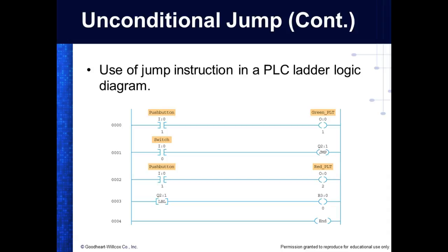What I was getting at within my mind, I'm battling. If I was looking at this in motor controls, every circuit has to be complete. Whereas the PLC is going to sit there and just scan for everything. But you can jump over rungs in ladder logic too. We're not jumping over outputs, we're literally jumping over rungs, and anything in that rung becomes not true. So there's very little we can do in PLCs that we can't do in motor controls.